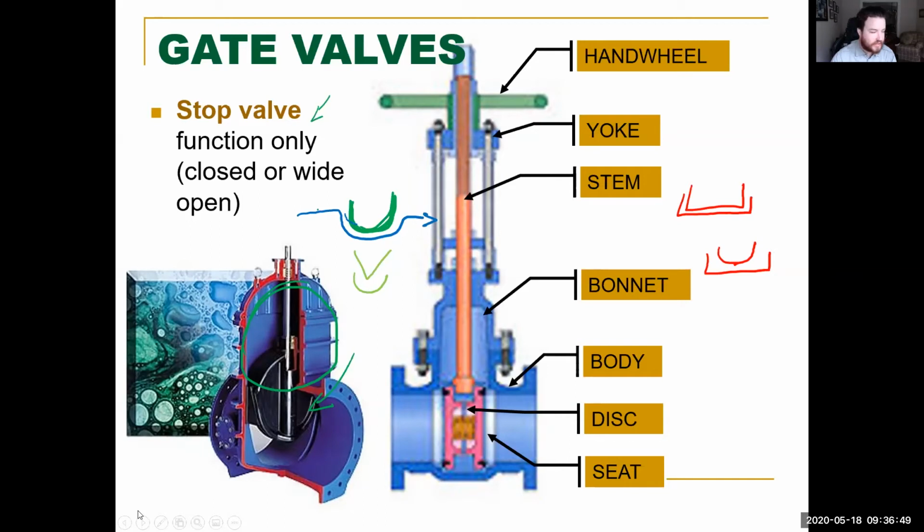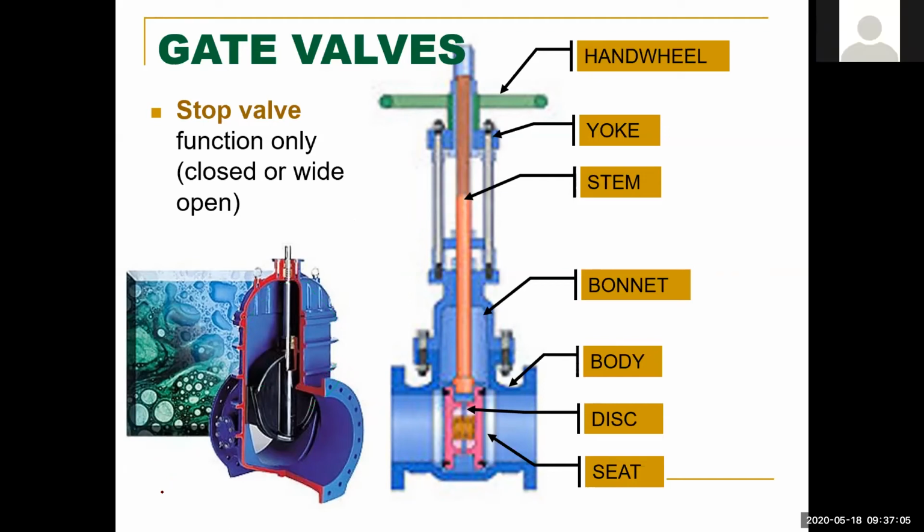And that's why you don't want to use these gate valves as a throttle valve. You can, but only in one particular instance can you use gate valves as a throttle valve. When would that be? Would it be for fuel? It can be for any system. Maybe in an emergency? Sure, in an emergency, anything goes. But it all comes down to valve arrangement.